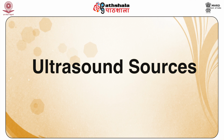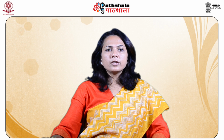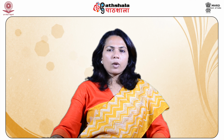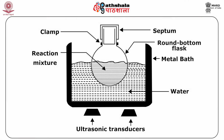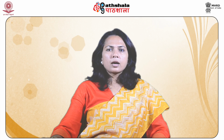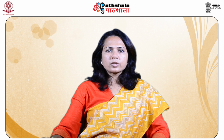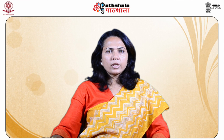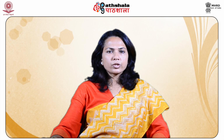Next, let us study the ultrasound sources. A variety of devices have been used for ultrasonic irradiation of solutions. For common laboratory use, there are three main designs, namely ultrasonic cleaning bath, cup horn sonicator, and direct immersion ultrasonic horn. The source of the ultrasound is a piezoelectric material made of lead zirconate titanate ceramic (PZT) or quartz, which